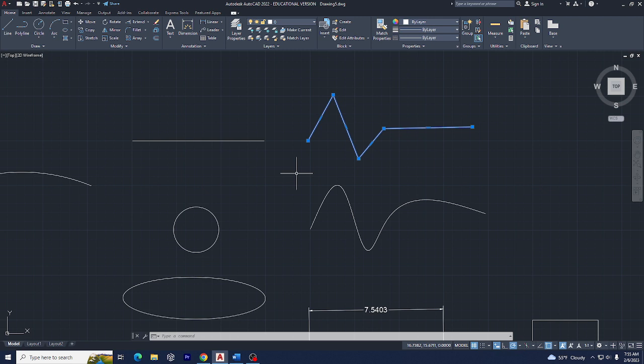So the grip menu: if you hover over a grip like this, you have options, stretch or lengthen. You can choose S for stretch, and then you can stretch it out as far as you'd like. L for lengthen, and instead of stretching the line, it'll lengthen it. It'll just move the line. I grabbed 2 there, sorry about that.